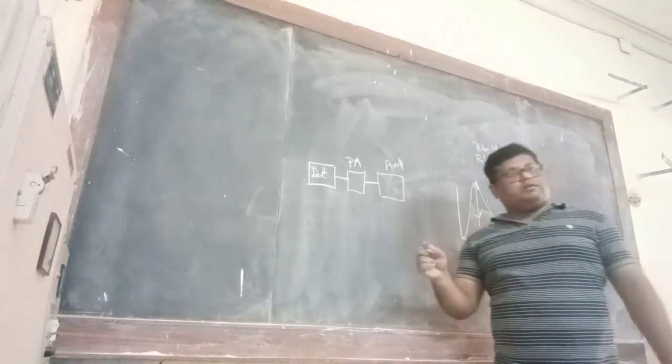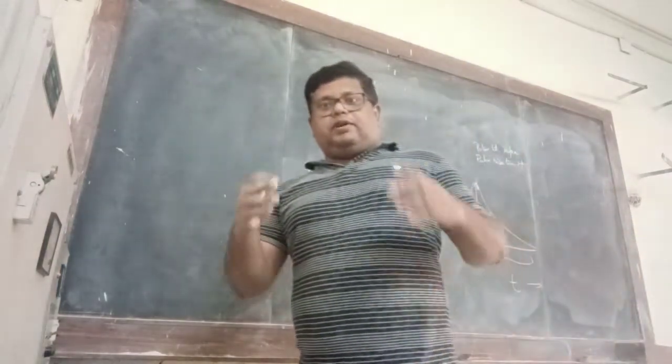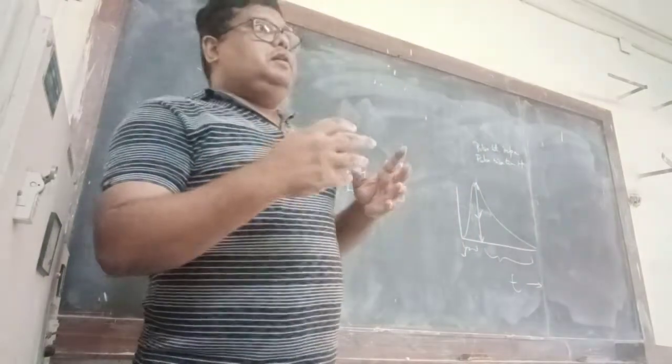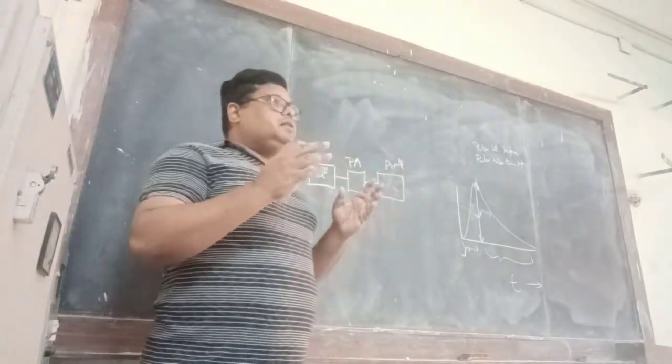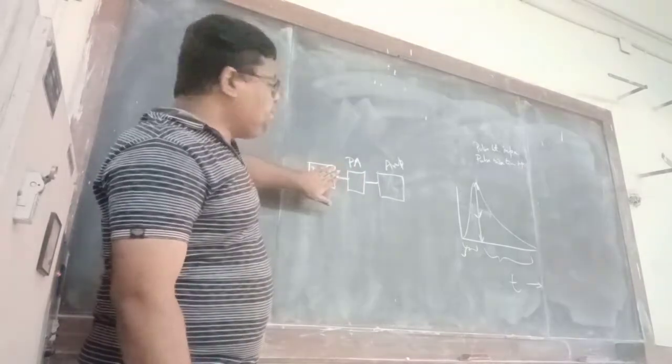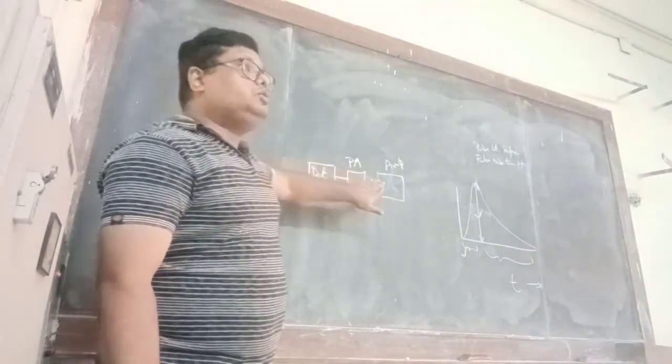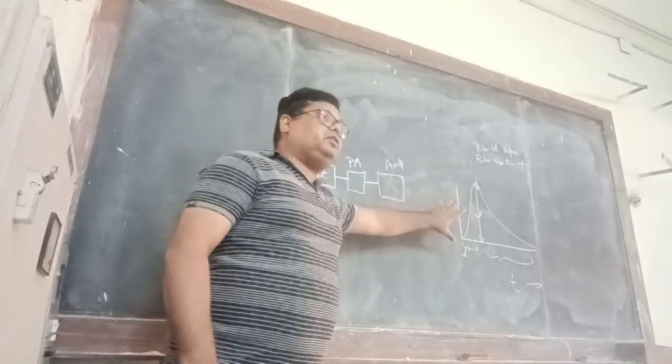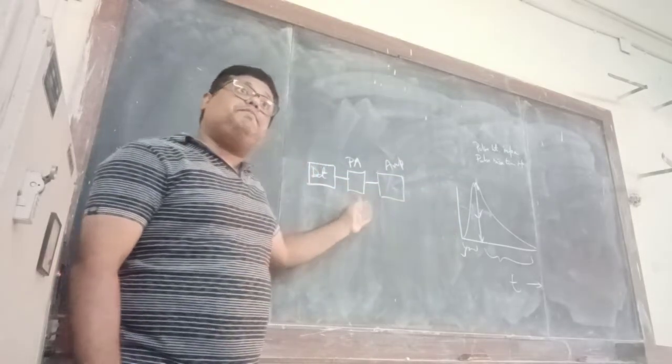Remember the maximum power transfer theorem? Power is transferred maximum when the impedances are equal. So what it does is it matches the impedance of the detector output to the input of the associated electronics. Okay, this is impedance matching.